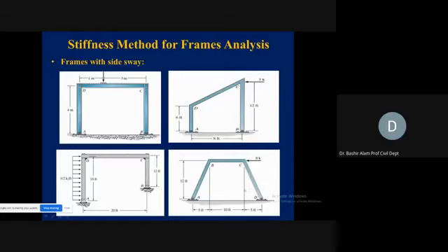If we look at the first diagram where A, B, C, D joints are shown, and this point load is 1 meter from the left joint and 3 meters from the right joint, it is unsymmetrical. Looking at other conditions, at the top we don't have any arrangement to stop the lateral displacement.